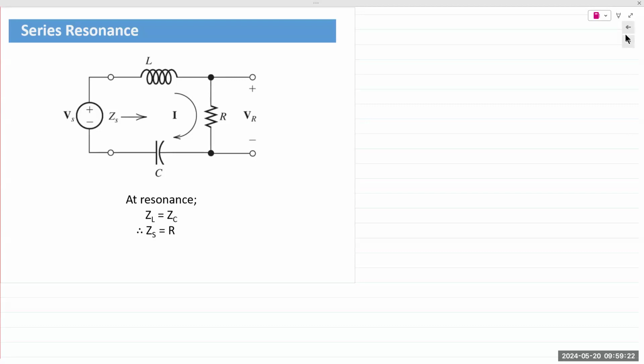Okay. Those of you who are taking the lab might have noticed when you performed lab 6, with an RLC circuit, the voltage across the inductor was larger than the source voltage. The reason is the source is sending some energy to the inductor, but the inductor also receives stored energy from the capacitor.